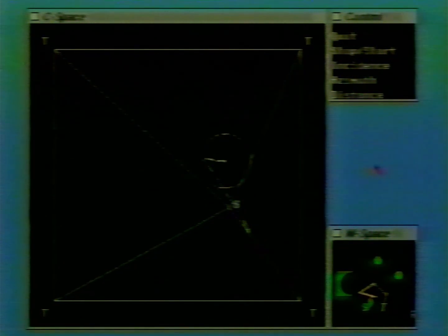These preliminary results relate to applying range sensing to the case of a robot arm. Unlike a mobile robot, whose radius of vision can be assumed fixed, the so-called vision for the arm manipulator, when transformed into the configuration space, becomes variable even if all sensors covering the robot arm have a fixed sensing range.